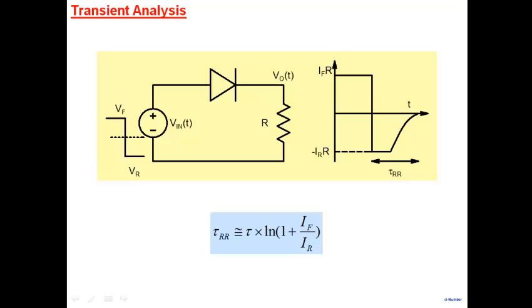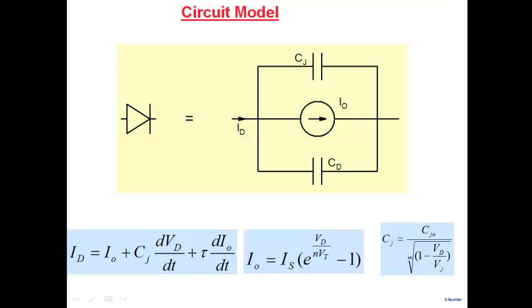If you take a PN junction diode and you switch it, you know that even in the reverse direction, it conducts for a short period, which we call the reverse recovery time. It takes a certain amount of time for the diode to recover its blocking state in the reverse bias case. This equation, for example, was stated when you did this experiment. We'd like to see where this equation comes from. How much is the reverse recovery time? What are the factors it depends on?